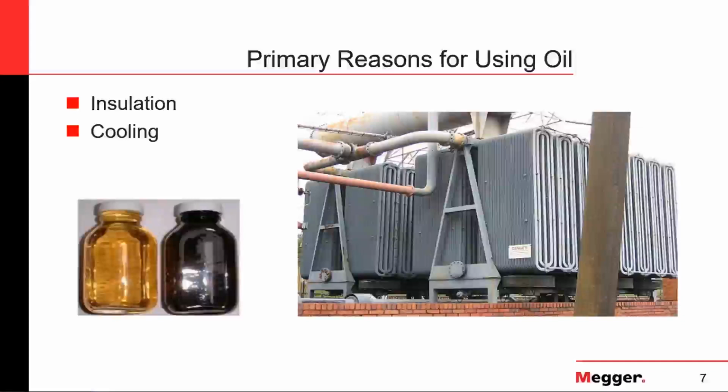If we think again of that same example, a power transformer, the internal part of the unit has to be completely dry, or in other words, completely free of water content, as this will help to prevent partial discharge inside the unit, which if present will eventually cause electrical breakdown when the transformer is in service.